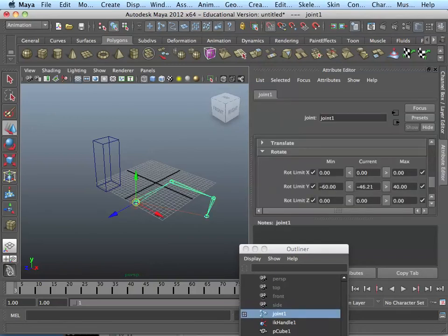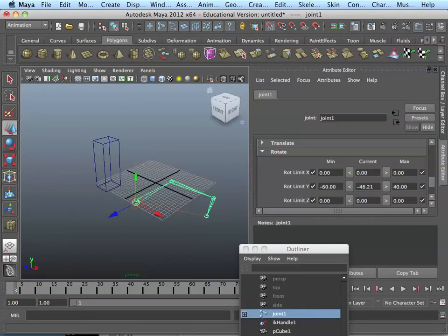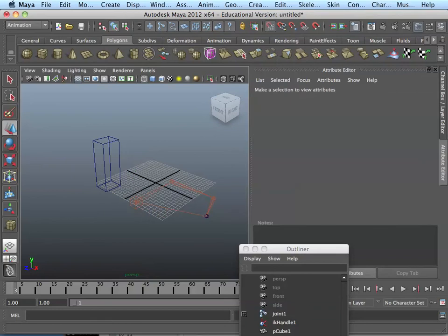So let's pretend I measured it, right? Let's say I figured out I got 100 degrees total. And when I start to calibrate this thing, I set it to 0, and this is where it's sitting, and I know that's going to be my minus 60, right? Like if I wanted to make these things match up, assuming this is your center line, negative 60 degrees. So negative 60 and 40, what I can then do